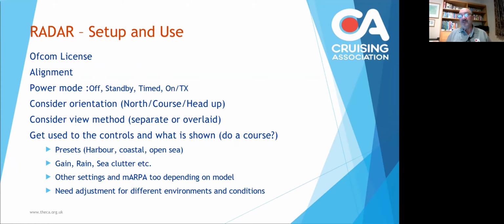It may have a preset for harbour, maybe for coastal, or maybe to open sea. And that will tweak things like the gain, the rain, the sea clutter, the things we'll talk about next. It will also change the alarm settings potentially. So look at the other controls, the gain, that is how small an object, it will make sure that it sees a reflection coming back from it.